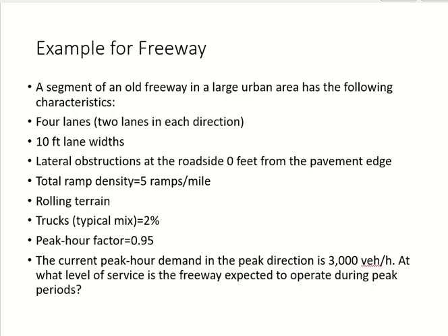This much width will not even be allowed in Bahrain for any highway. Even when you are doing construction work, they would prefer to have at least more lane width than this one. So, because of the narrow road, even free flow conditions are having very poor level of service.